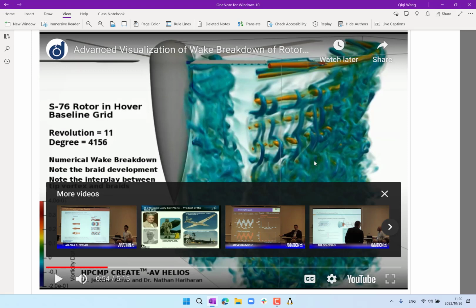The way I think about it is, what is the sense of the circulation around this rotor blade? A rotor blade is generating positive lift, right? So the flow above it has to go faster, low pressure. So if you look at this blade, the circulation has to be that way, right? And then the vortex coming out of the tip is a continuation of the circulation on the blade. So when you think about this and it comes back, the circulation has to be like that. All right?